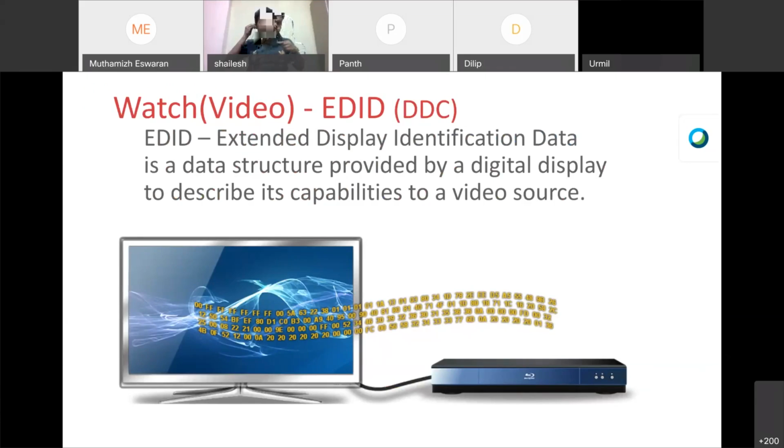Okay. And then of course, whenever I connect any HDMI source to a display, the first thing is my source will send authentication. There is a 5-volt line in your HDMI. If you have a source which is connected and powered, your source will send a 5-volt trigger to the display, and the display will send the information it wants for the HDMI. It will say this is my resolution, this is what I can play. If you can support that resolution, definitely you can get it back. So that's the basics of any HDMI, right?